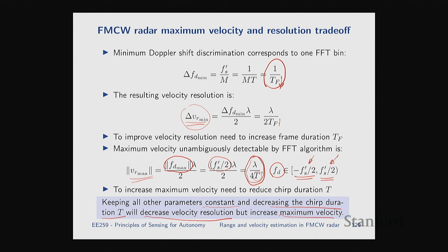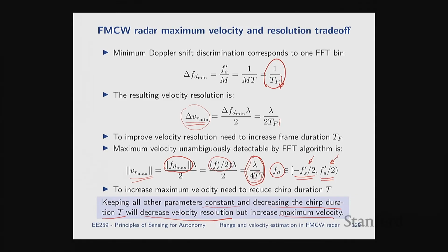Why in this case, for the sampling of the Doppler, is it quote unquote Nyquist, I guess? Why is it fs over 2 and not just fs? Well, it is Nyquist, but it is minus fs over 2 to fs over 2, because if this is my frequency axis after the FFT, and that's 0, Nyquist tells us you have to be within the sampling rate before things start to wrap around.